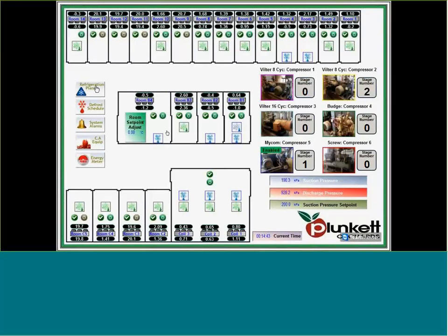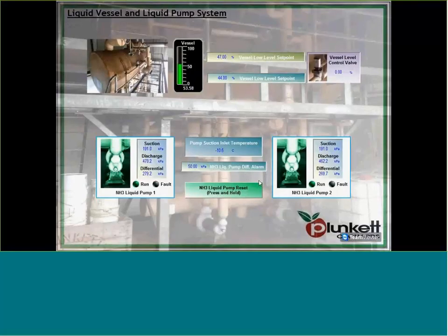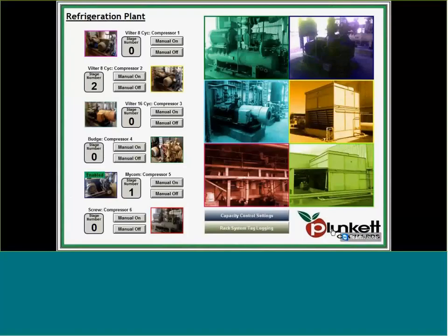In the refrigerated plant room, we move to this screen, which shows a lot of visuals. So the plant, the actual physical pictures of the plant we used, so people could tell what area of the plant they were looking at. This really helped out with things like the liquid pumps, so people could actually look at the photo, see what the liquid pump was, and go and see when general faults had occurred. We also used a few general symbols there, straight out of the Indusoft library. Worked great.